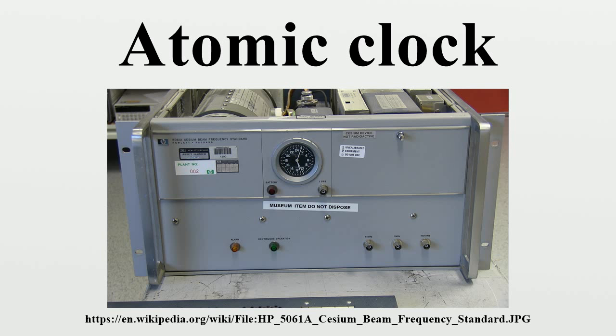Modern rubidium standard tubes last more than 10 years, and can cost as little as $50. Cesium reference tubes suitable for national standards currently last about 7 years and cost about $35,000. The long-term stability of hydrogen maser standards decreases because of changes in the cavity's properties over time.